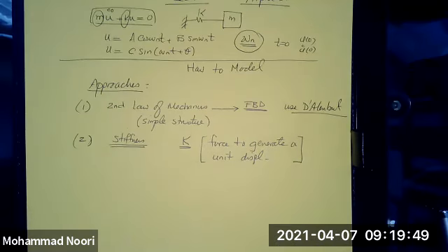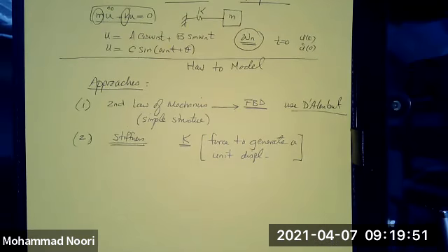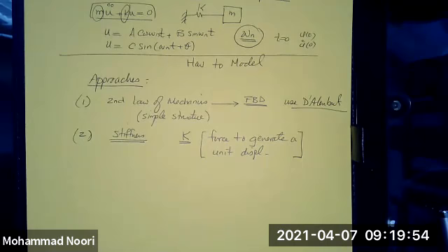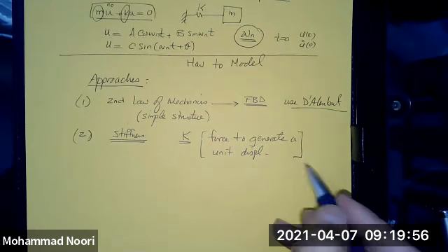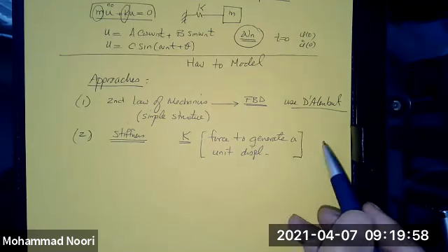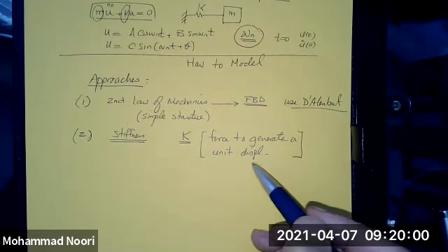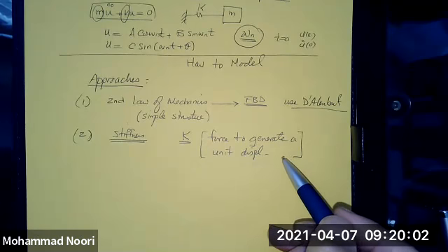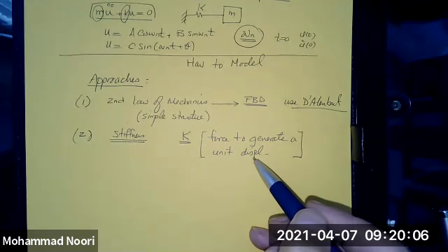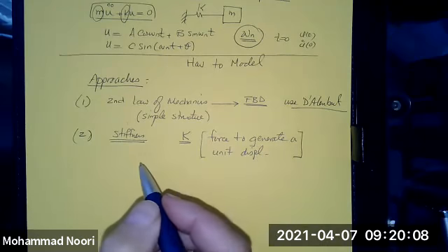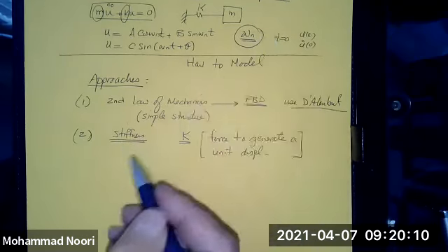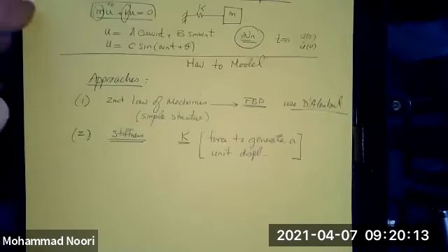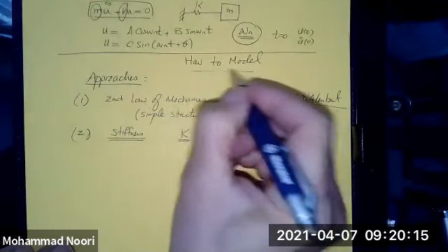You've seen that in the strength of materials and so on, that by using a simple structural analysis, that is, using a force that generates a unit displacement, you can easily find the stiffness in a system. And if you find the stiffness, you can then set up easily the equation of motion, okay?